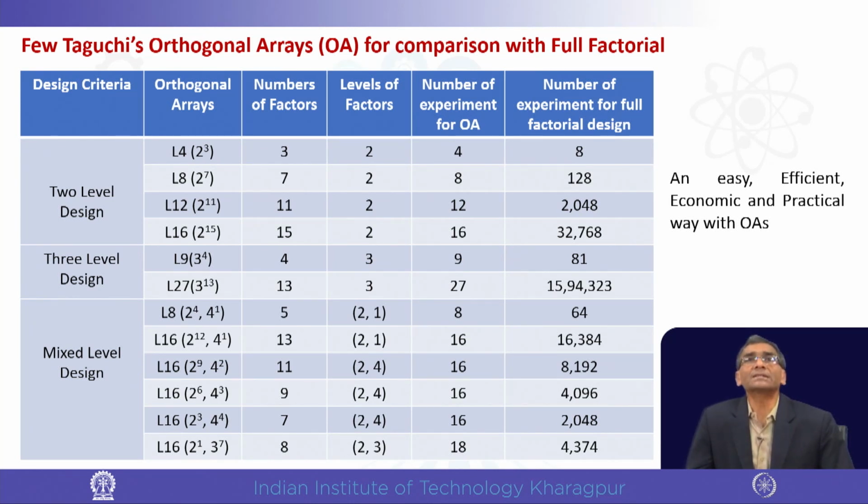Now, just see another thing. Say there are 3 factors, then with 3 levels, maximum, medium, minimum, for example, we would have to carry out 81 experiments, where Taguchi suggests an array through which it is done with only 9. Fantastic results.